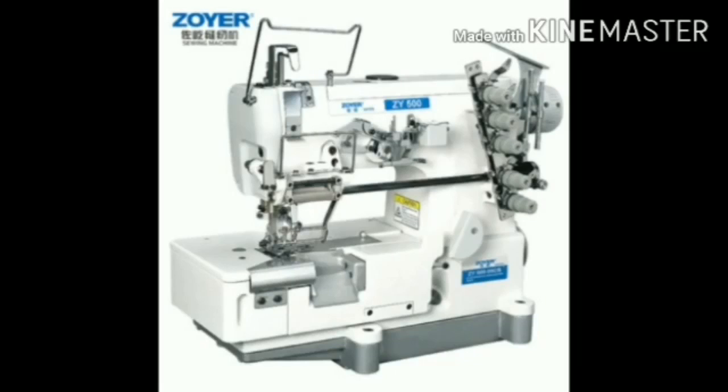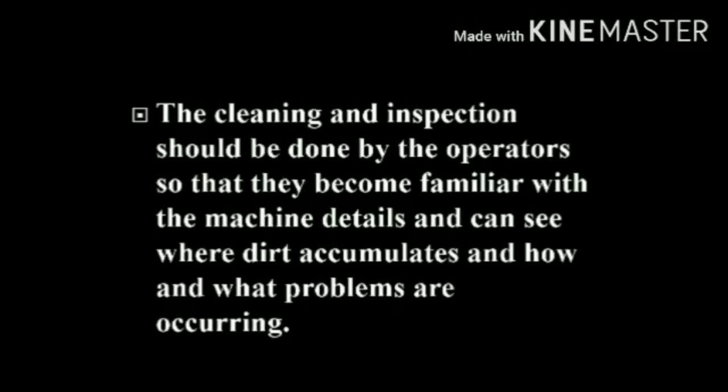It includes the thorough cleaning of the equipment and its surroundings. The purpose is to ensure that the machine performance is fully restored by identifying and eliminating all signs of deterioration. The cleaning and inspection should be done by the operators so that they become familiar with the machine details and can see where dirt accumulates and how and what problems are occurring.